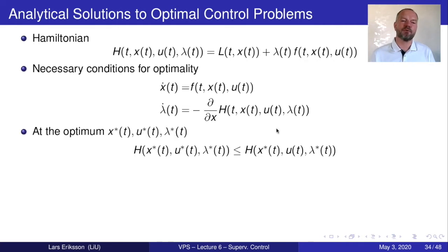Now we come to the most important point for solving this, and that's when we have the optimal state trajectory, we have the optimal control trajectory, we have the optimal co-state trajectory. Then, through Pontryagin's minimum principle, they prove that this one will always be minimum. We can never find a control signal that improves and goes beyond this. So with this, we essentially change the problem from being a global problem so that we can look locally.